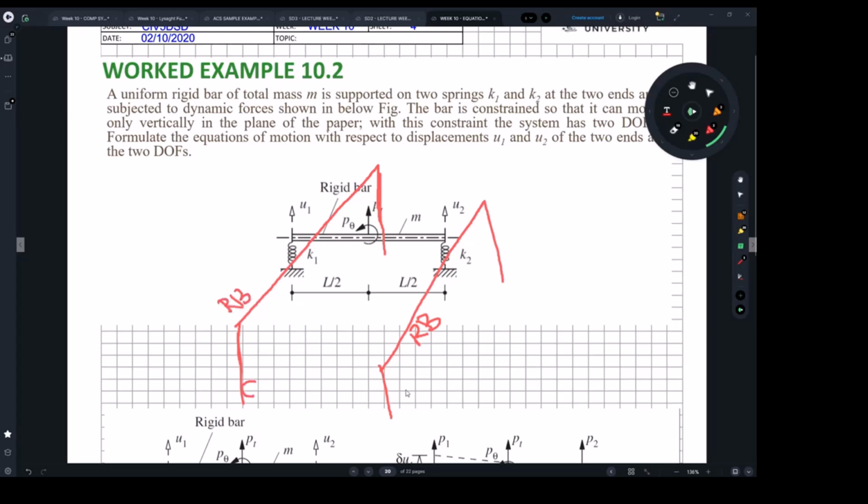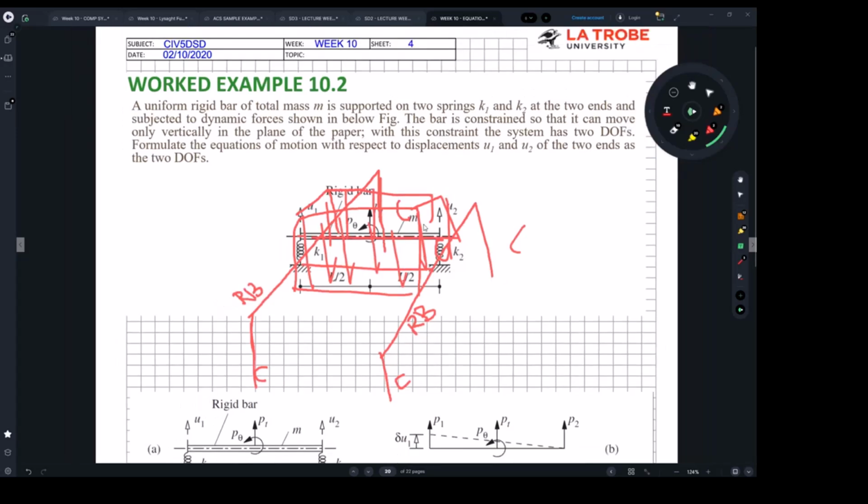And this is just a column. Usually we are able to estimate a stiffness as a spring for this roof beam, because it will be acting as a spring. Same thing here, and we need to support the units. There are going to be maybe a couple of beams, and all those beams and the chillers on top are basically that unit I was talking about, which we need to study for its dynamic influence.